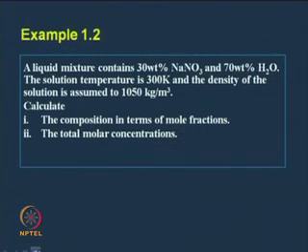Now, let us take another example to calculate the mole fractions and total molar concentration. A liquid mixture contains 30 weight% sodium nitrate and 70 weight% water. The solution temperature is 300 K, and at this temperature the density of the solution is assumed as 1050 kg per meter cube.